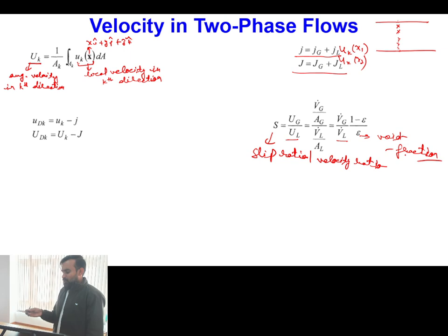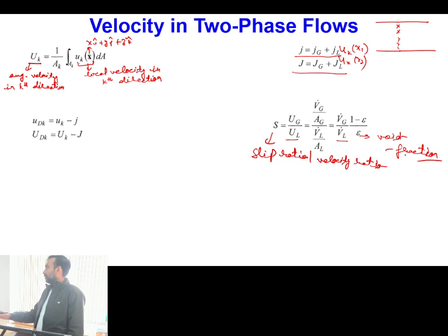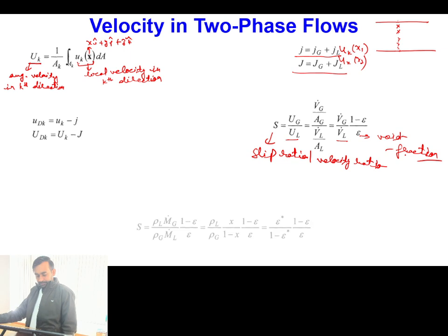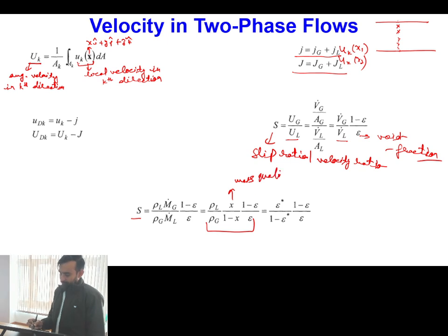Slip ratio sometimes becomes essential in defining the value of drag, lift and other types of forces exchanged between the dispersed and the continuous phases. This is again a representation of slip ratio in terms of mass quality and void fraction.